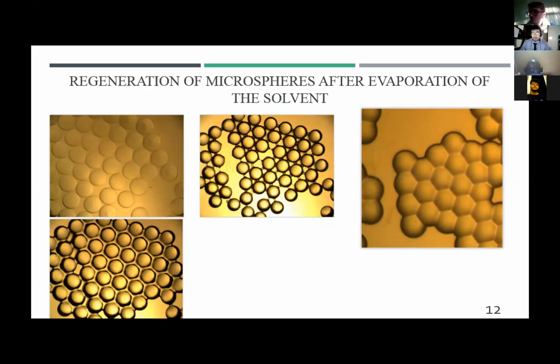The studies have shown that tensile deformation of polymeric films with a thin layer of hard coating applied on them is accompanied by the following general phenomena: the appearance of regular micro-relief and regular destruction of the coating. It has been found that the micro-relief is always oriented along the axis of tension of the polymer support and is positioned perpendicular to the cracks of the damaged coating. Observation of processes in model systems of polystyrene microspheres with sizes of 6 to 100 micrometers can lead to a number of conclusions about their behavior after the application of analyte vapors.